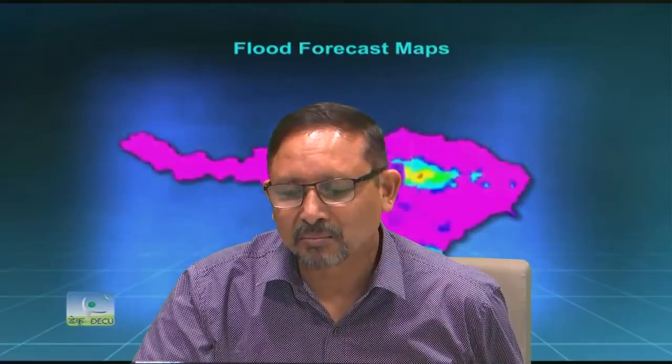So DEM-derived input parameters are used in flood modeling. You know that if the slope is more, the movement of runoff water will be high. So how much slope percentage there is, how much area is under depressional land or valley area, this information is very useful for flood modeling. So DEM is an important input parameter of flood modeling. And for watersheds in natural calamities, suppose the natural calamities are drought, or landslides, landslips, or where more runoff water is flowing, because of that flash flood type situations are also created.